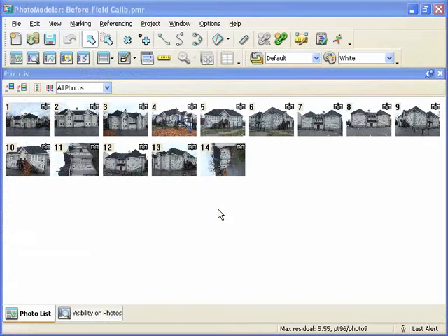To help fine-tune a project, especially if your calibration is done at a drastically different size than the project size, you can use an option called Field Calibration. Field calibration uses your project's data to adjust the existing camera parameters. To perform field calibration, your project should already be solving relatively well.